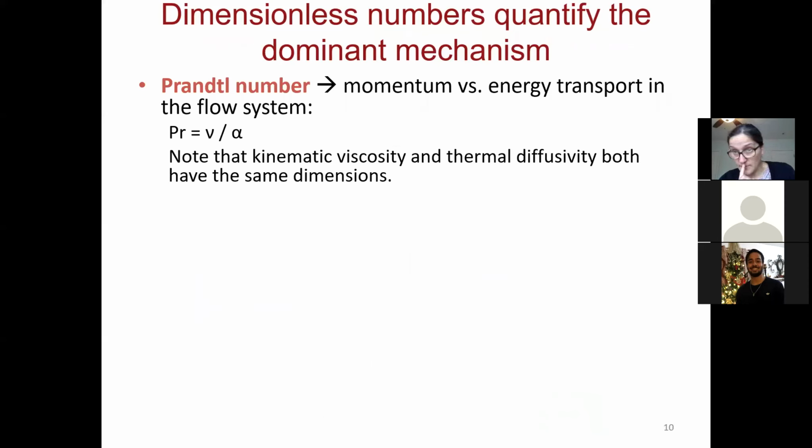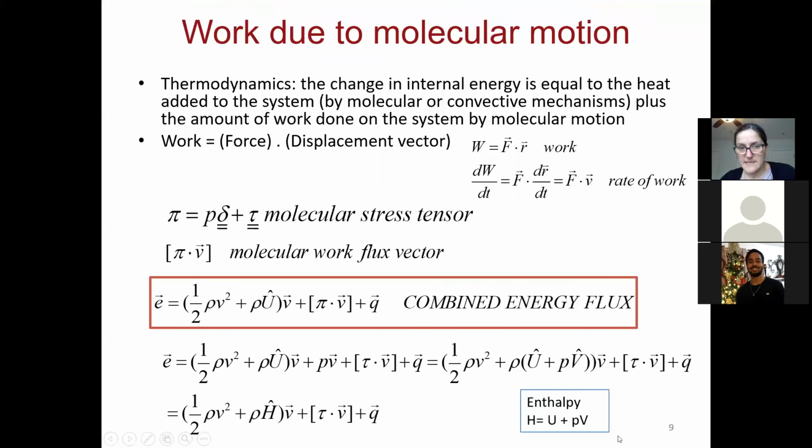So one thing that we will have to be overall careful about is, what is the transport that is dominant? For instance, if you look at the differences in temperature that are driving the heat flux, that's what's quantified by Q over here. And then there's stuff that is happening in the fluid. It is rather important to know: is this 10 times smaller than this, or is this 100 times smaller than this, or is it the other way around?